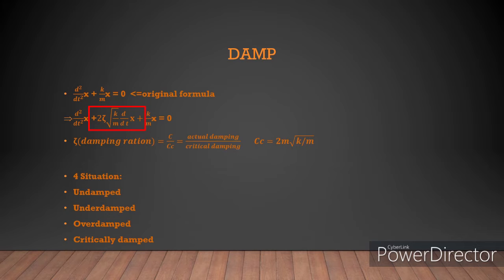The damping ratio characterizes the frequency response of a second-order ODE. In general, a system with a higher damping ratio, 1 or greater, will demonstrate more of a damping effect. The damping ratio provides the level of damping in a system relative to critical damping.